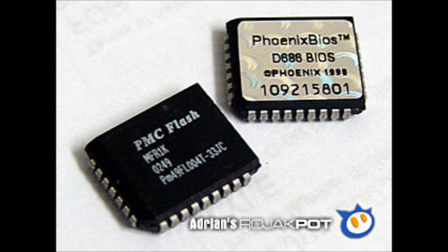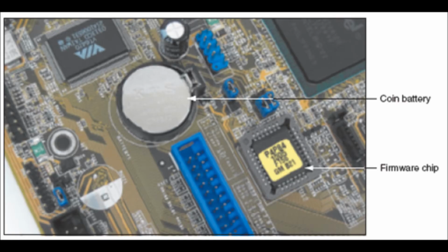For instance, a ROM chip on an adapter card inside your computer has software instructions permanently etched into it during the fabrication of the card. This software is actually part of the hardware, and it is not easily changed. In this case, hardware and software are closely tied together, and it's difficult to separate the two, either physically or logically. Software embedded into hardware is often referred to as firmware because of its hybrid nature. The accompanying figure shows an embedded firmware chip on a motherboard that contains the ROM BIOS programs.